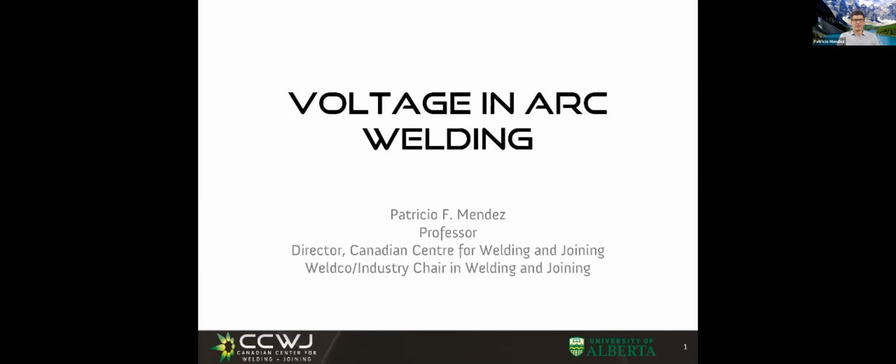Voltage in arc welding. We just discussed the welding arc, and we said how the arc has three components: the cathode, the anode, and the column. And we assign voltages to the cathode, the anode, and the column. And those voltages are pretty much what dominates the voltage you would read in the panel of your welding machine. And the examples I had so far were about TIG, because TIG was easy to explain in this context.